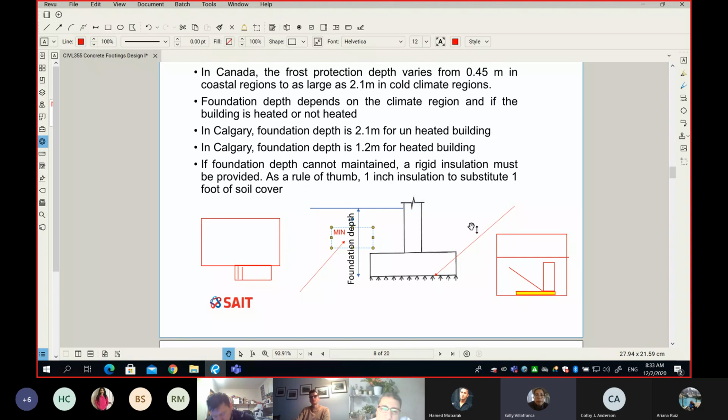That is the minimum point that you can go down. Yeah, but this is a protection for ourselves because simply, number one, it is dictated by the frost height or the frost depth. And in addition to, we need to make sure that we have enough bearing capacity. So we say go to 1.2 meter. If you find a good soil, great. If you cannot find a good soil, what you do is you go even down more than 1.2 meter.